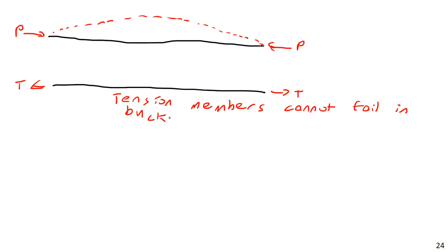So then, the question is, how slender can you make them? Well, the AISC manual does not provide any code that says, okay, for strength reasons, if you make your tension member too slender, it's going to snap in half, it's going to break, it's going to buckle. This is not that kind of limitation. This is more a practicality or constructability type of thing. So the longer and longer things get relative to their width, their cross-sectional area, their moment of inertia, etc., the more flexible they get.